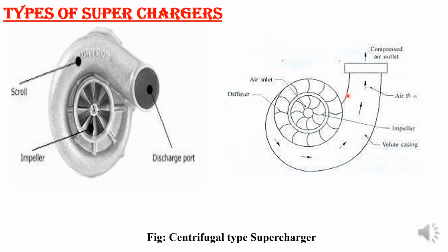The figure shows a centrifugal compressor, which consists of an impeller rotating in a close-fitting casing. The air enters above the impeller axially. You have seen this in turbomachines. So above the impeller, the axial entry will be there, and the air is turned exactly 90 degrees. It is turned by the vanes of the radial impeller or diffuser ring.